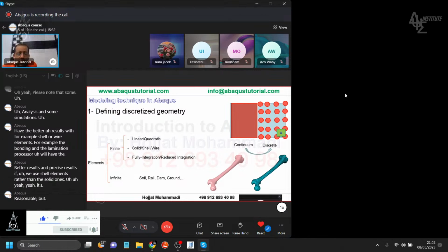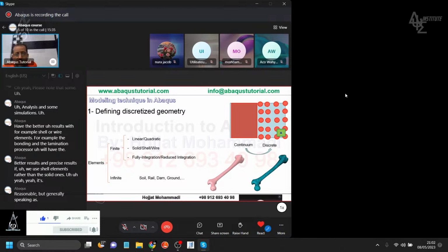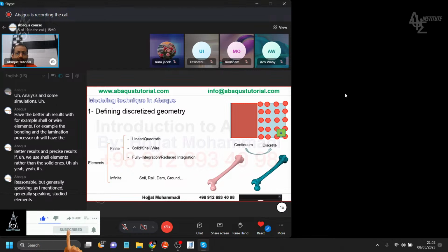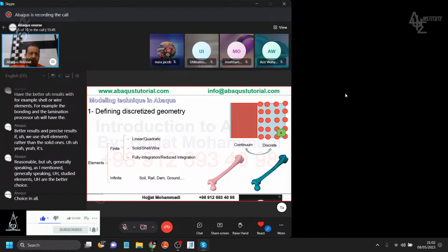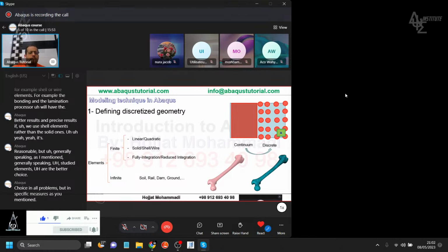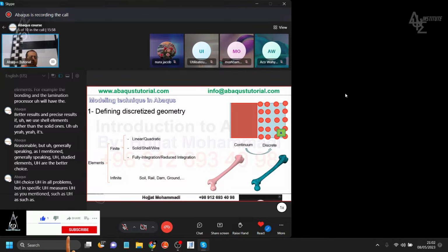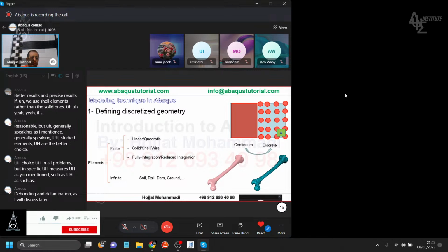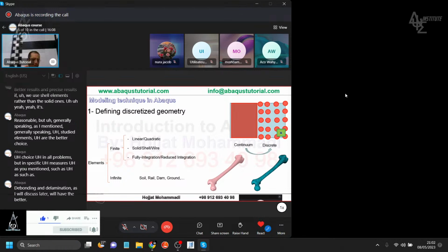But generally speaking, as I mentioned, solid elements are the better choice in our problems. But in specific cases, as you mentioned, such as debonding and delamination, as I will discuss later, shell elements will give better results.